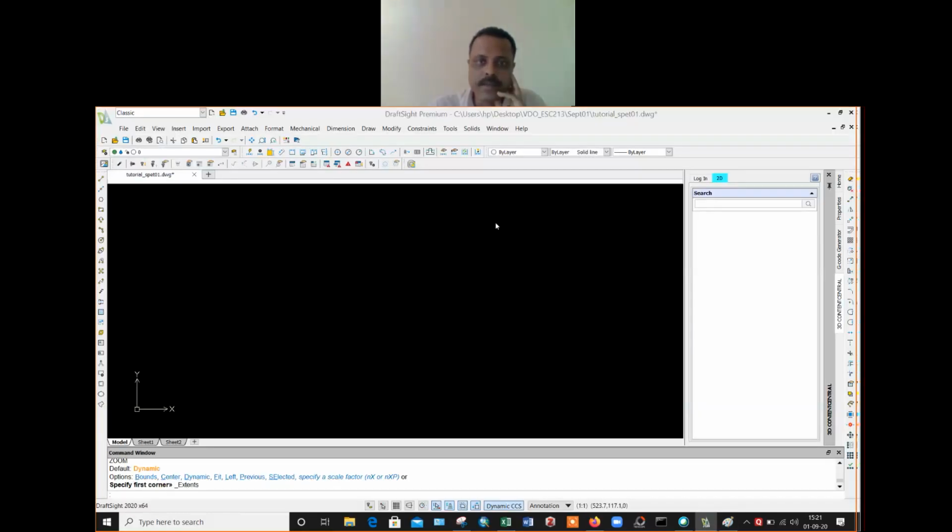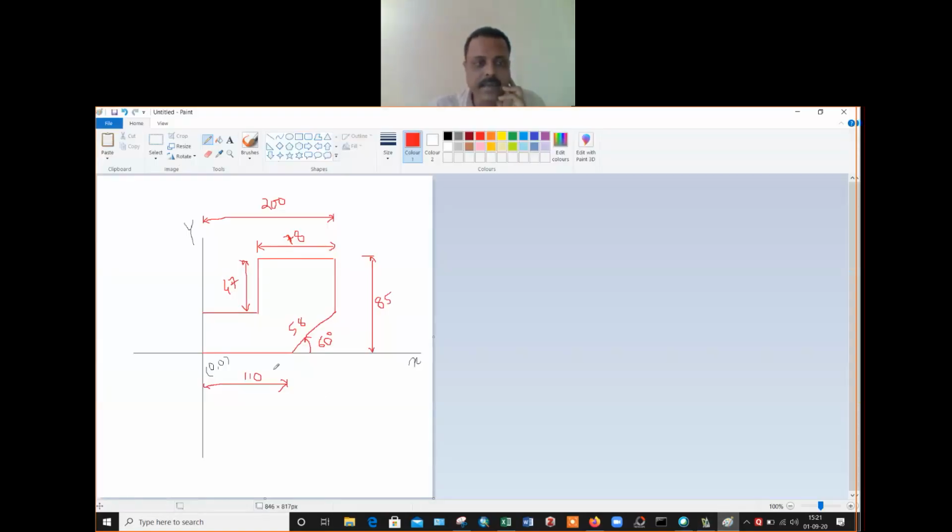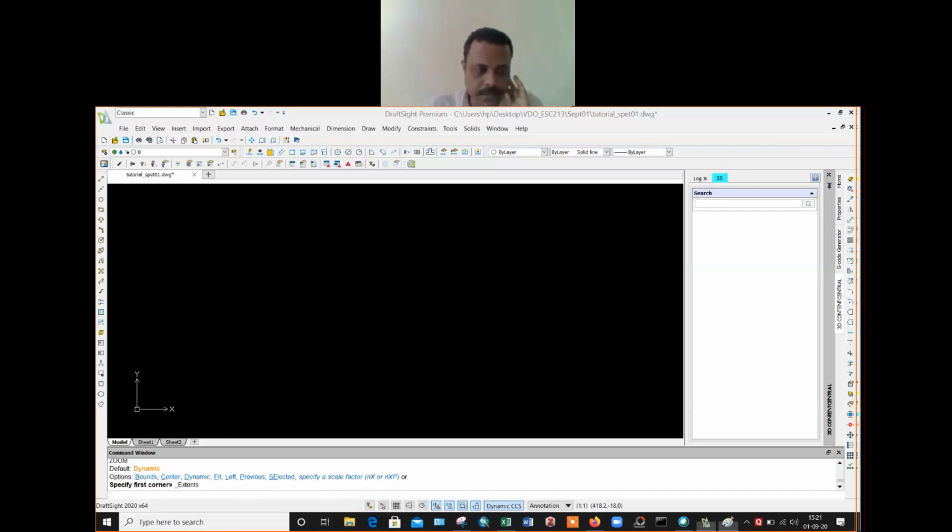So again, going back to the drawing board. Remember, this time I am specifying that I have my origin 0, 0, and this starts from the origin. This is 110 millimeter. So for that, I need to start with the line. For line, I need what command? L. Type enter.